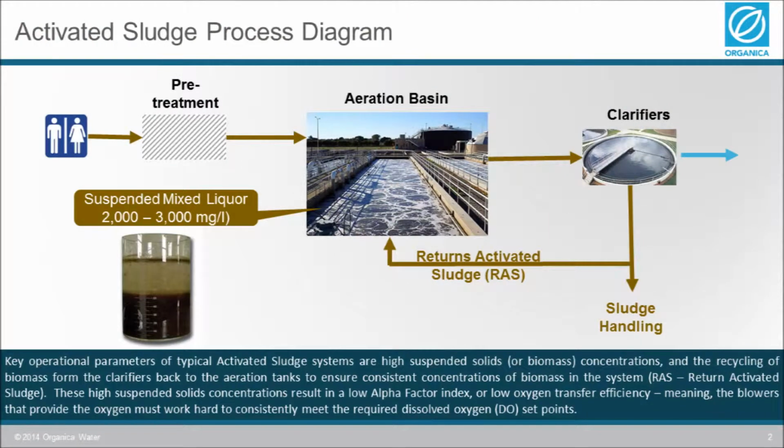But specifically looking at return activated sludge utilization, it is where the solid separation, most commonly a clarifier, collects the mixed liquor biomass in the bottom of the clarifier, and then a portion of that is recycled back into the biological process that allows the organisms to grow and maintain a specific age, if you will, commonly referred to as sludge retention time or mean cell residence time, SRT, MCRT.